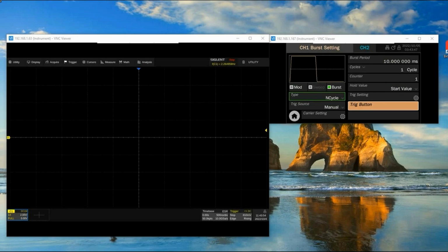There is a video already on sequence mode directly, so I'm not going to go into gory detail about that. But I would like to let you know that there's a really easy way to set a number of frames. Once that number of trigger events has been captured, the instrument will automatically go into stop. I'd just like to quickly go through that.